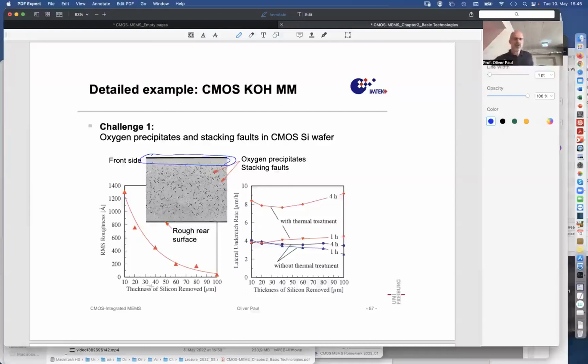And then also we have removed silicon at the backside, in order to make it flatter, so that the rear protection layer that is needed for defining the membranes adheres better. And so we have analyzed the root mean square roughness of the rear side in angstrom, and then you saw how with that polishing process the backside became smoother and smoother.